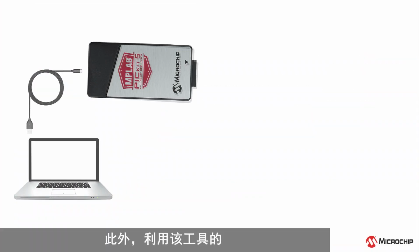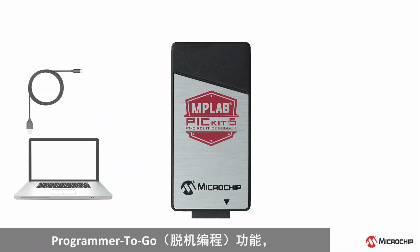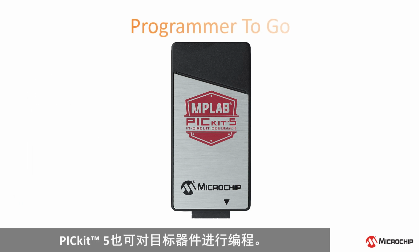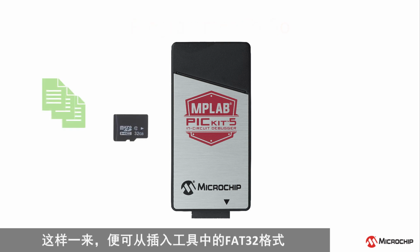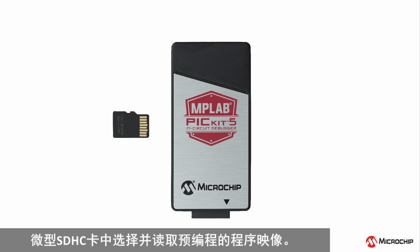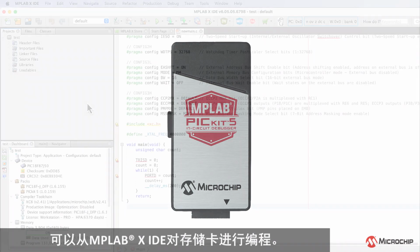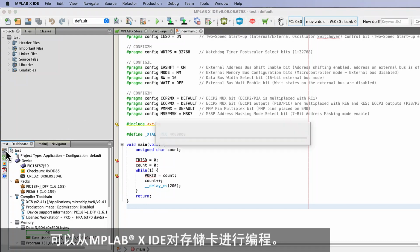The PICkit 5 can also program targets without the need for a host computer, using the tool's Programmer-to-Go feature. This allows one of several pre-programmed program images to be selected and read from a FAT32 formatted micro SDHC card inserted into the tool. The memory card can be programmed from the MPLAB X IDE.